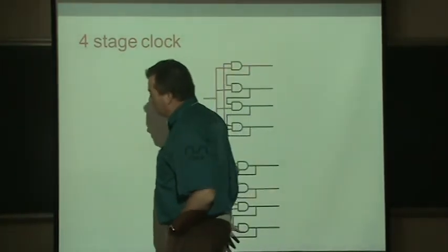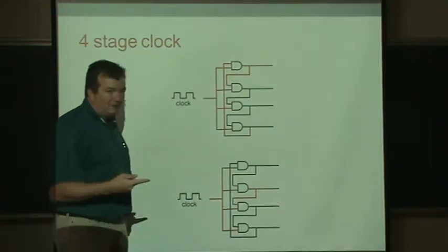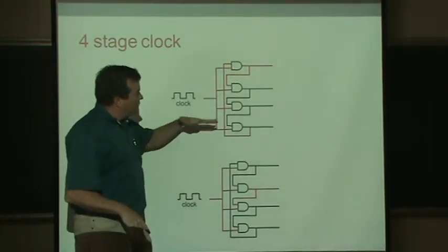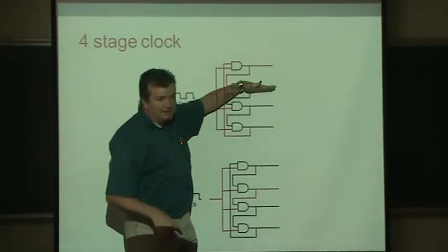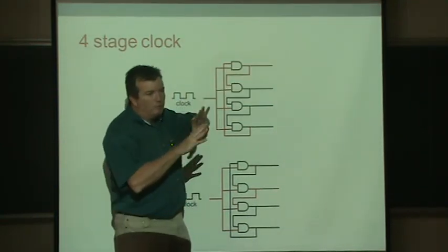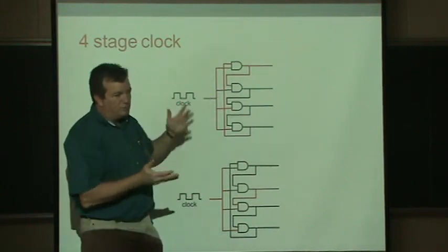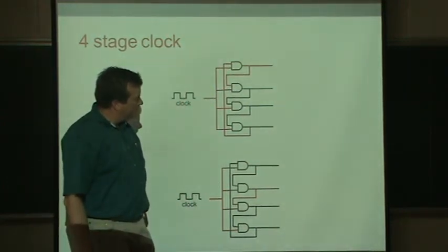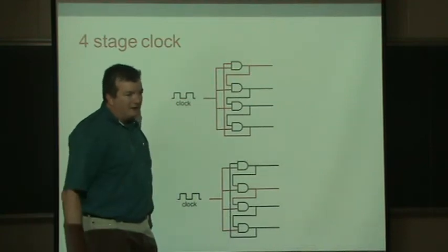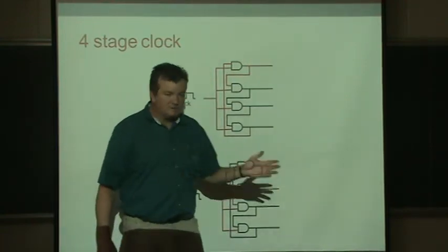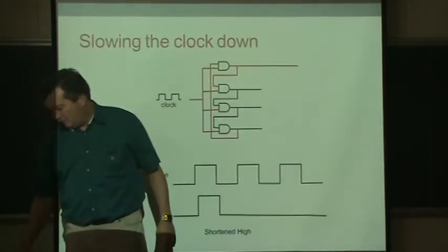But generally, that would never work if we started pipelining, because pipelining requires that stage 1 of one instruction is happening simultaneously to stage 2 of the next instruction, and therefore all stages would have to be the same amount of time. So we couldn't have variable amounts of time for different stages, slower stages getting more time. Okay.